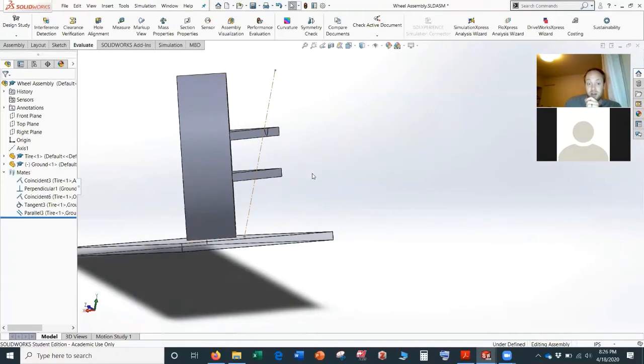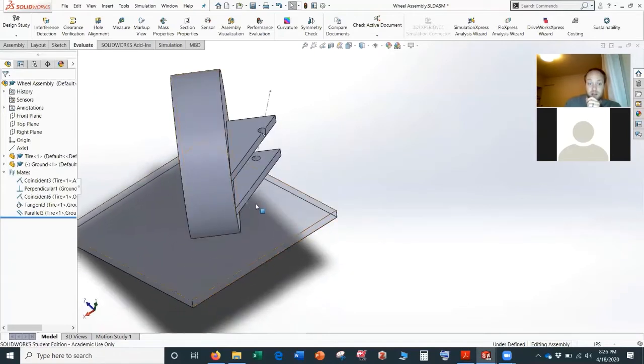And you see how, because the tire is here and this steering axis comes down here, the distance from the center of the tire to where it comes in is affected by the scrub radius. So in actuality, you notice that the trail and the scrub radius play together a little bit. And I think that's an important thing to note with all four of these: there are no set numbers for any of them, and you can't just say one should be this. It's really all four interplaying together.